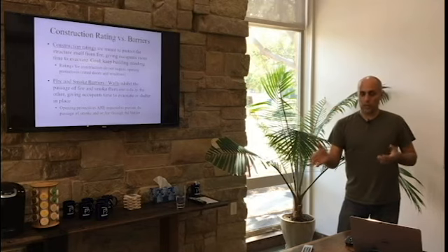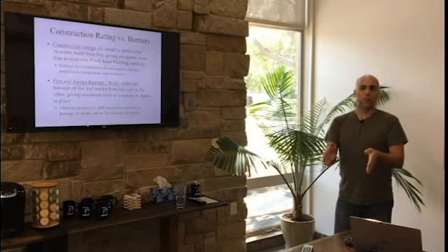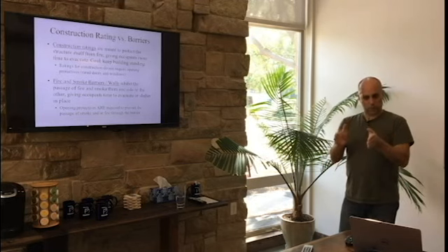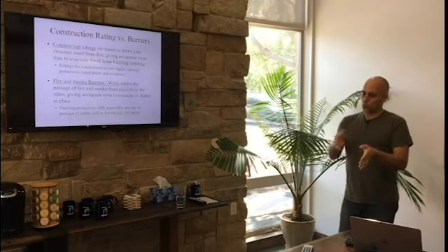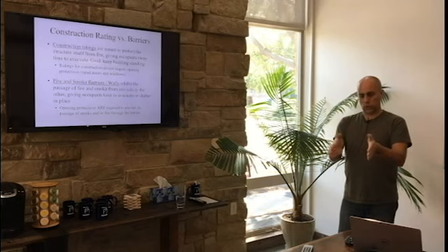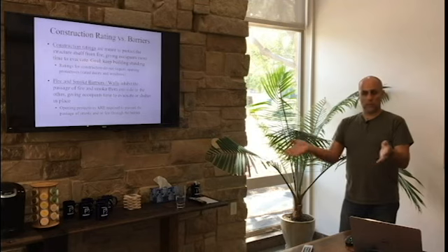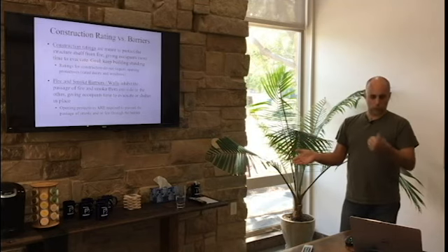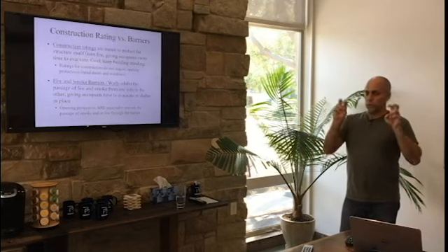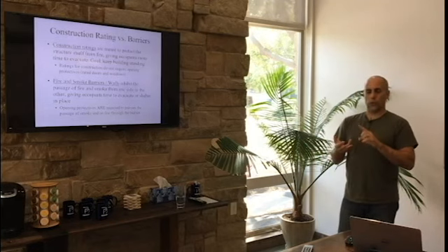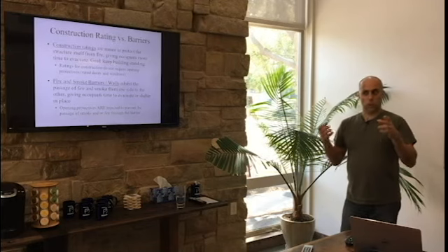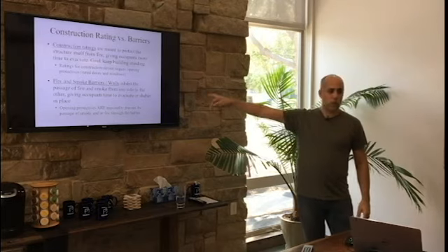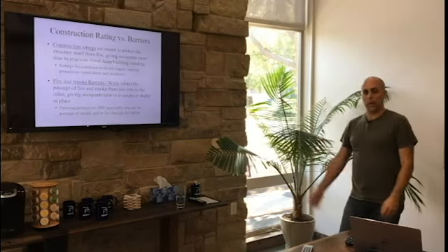Well, they might be an hour rated because they're bearing walls. They've got to stay up. But because they're not a fire barrier, meaning they just have to resist the passage of smoke, the doors in the resident rooms, which is usually the doors that are in our corridors, they're unrated. They just have to close securely in their frames, keep the smoke out. That's it. They're not self-closing, they're not automatic closing, and they're not rated. They're basically equivalent to a 20-minute door in construction. They're 1 3/4 inch solid core doors, but they're not rated because the wall is not rated for the purposes of separation. The wall is rated because it's a bearing wall.